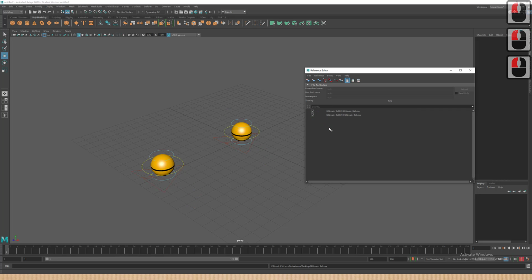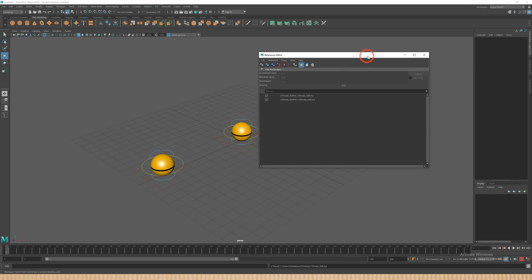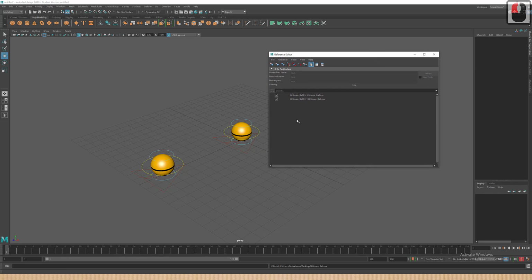These kinds of scenarios happen when we have a basket full of balls being thrown from some top angle, so that you are able to animate the interactions between them. That's the reason we use reference editors. Normally we don't open files when we are animating, we always reference them. So make sure you understand this idea whenever you are animating. Always reference your files, which will minimize your fatal errors for any kind of animation.